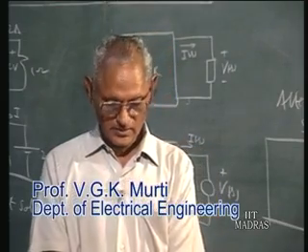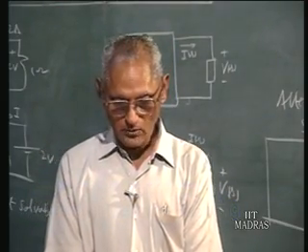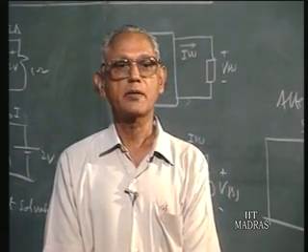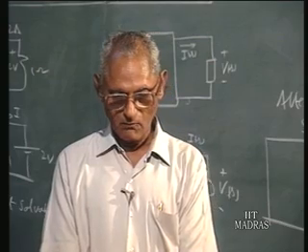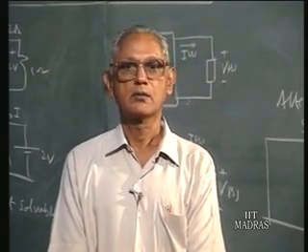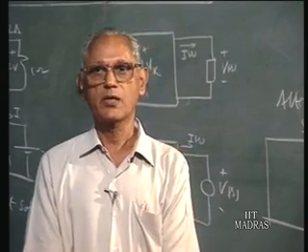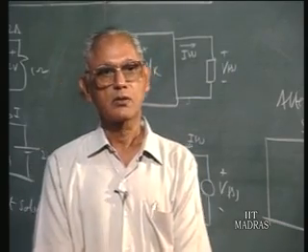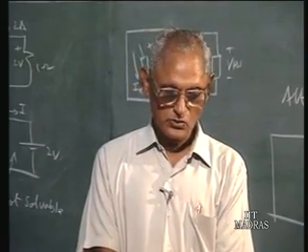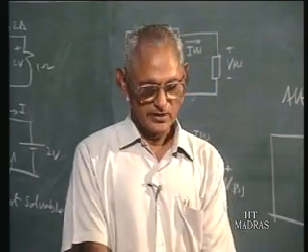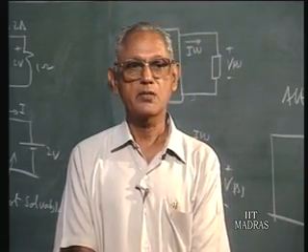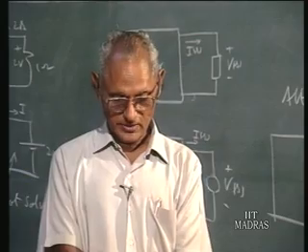Secondly, we observed that when you want to find out the transient solution in a network, then the superposition principle can be applied with 0 initial conditions in the system, or with all initial conditions replaced by equivalent sources, and therefore the principle of superposition can be extended to the sources which stand for the non-zero initial conditions. And this is what we do in the Laplace transform domain, where non-zero initial conditions are replaced by equivalent sources.